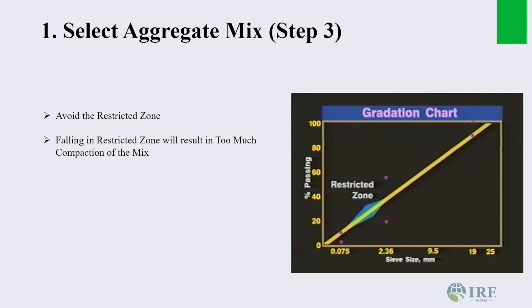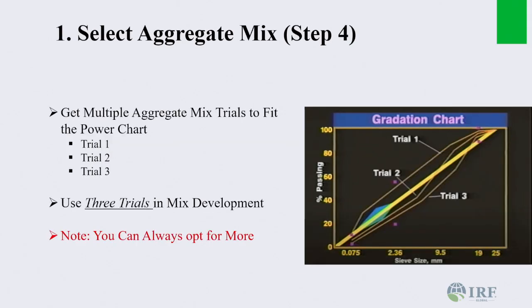And like Prof said, if a mixture falls within your restricted zone, you will have problems. Basically, with compaction of the mix, but also even rutting challenges that you are going to have. So just avoid the restricted zones.